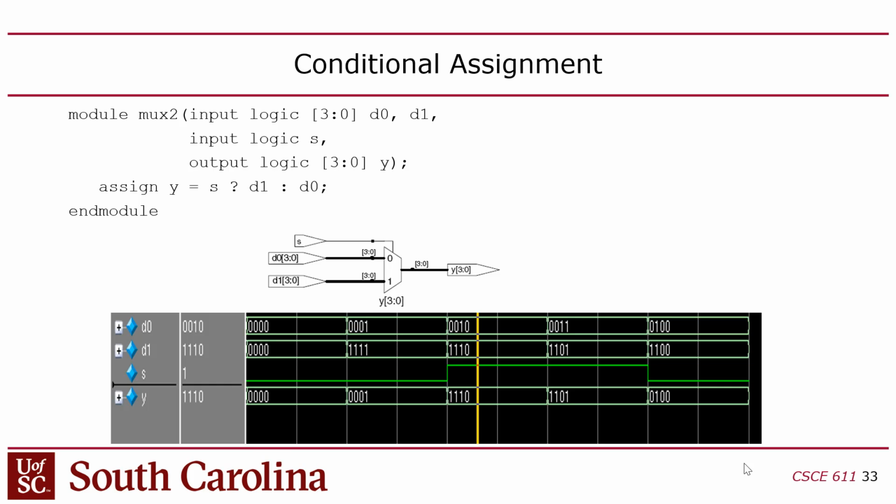You could say that, and if you do that, then the 0 select would correspond to the first input listed. Because I didn't put an equals here, this mux is a little confusing, because the first clause, D1, is actually going to be the second input on the mux, the 1 input. You guys with me on that?